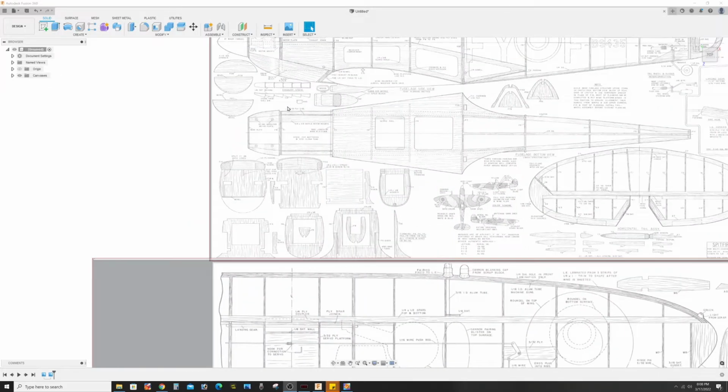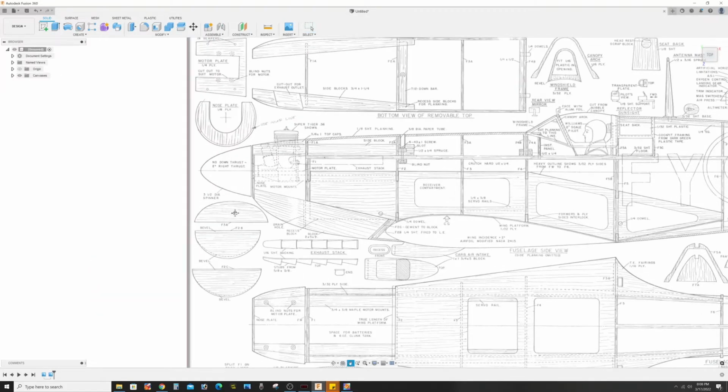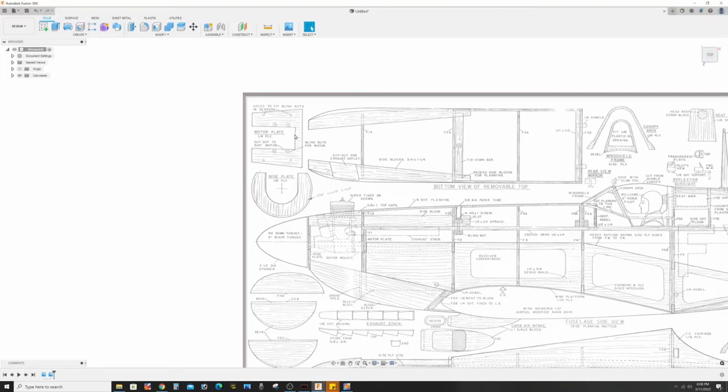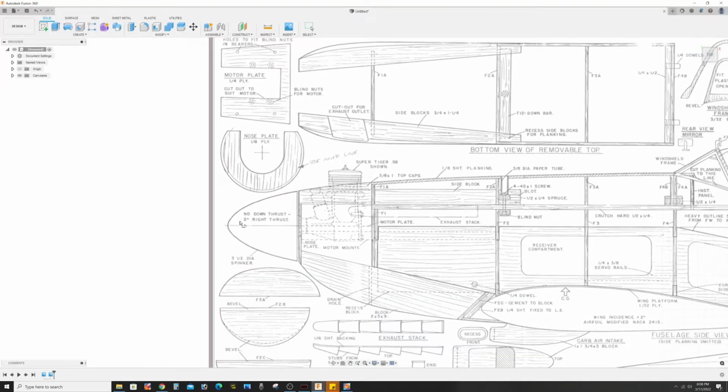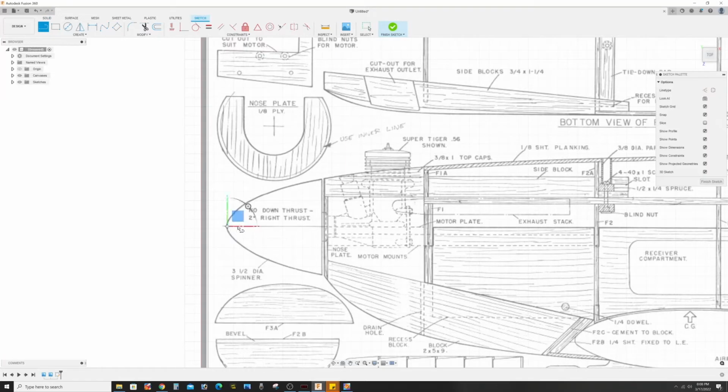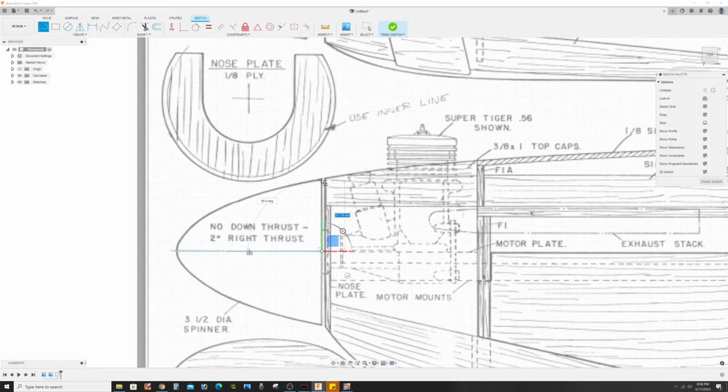This one is the revolve command, and this is for cylinder type objects. So first you would draw your line, your outline of your part, just like you would. The only difference is you're not doing a full outline. You're only going to do a quarter of it because we're looking at a cross section, and you need to revolve around a center axis. So the center, when you split your part in half, when you draw it, just like I did, that center line is going to be the axis that you revolve your part around.